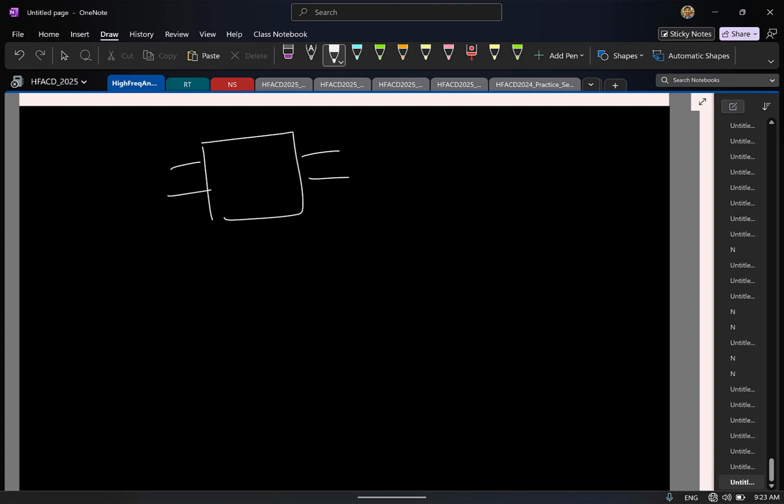If you have a fully differential circuit, to find the input referred noise power spectral density, you construct the differential mode half circuit, right? And then find the input referred noise of this differential mode half circuit. Let me call this SVN tilde of f. Once you know the power spectral density of the differential mode half circuit, you multiply this by 2. That gives the input referred power spectral density of the fully differential circuit. That's all.